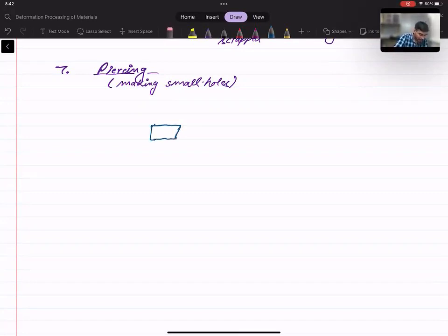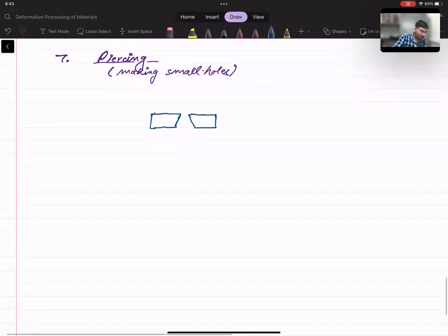In case of piercing, blanking, punching, etc., dies are kept a little tapered at the bottom side from where the cut out part or punched out part falls, because they act as an allowance for it to fall down. If it were straight, then after blanking or punching, the punched part will be stuck into that cavity or portion. So these dies or the holes are slightly tapered towards the bottom section, like the one shown in this schematic.